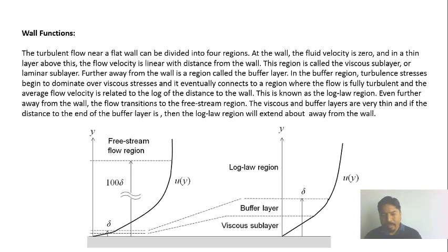It is very important while performing any computational fluid dynamics simulations to know how to capture the wall, and how we need to treat the wall. When we perform a CFD analysis, we need to understand how to give the wall functions, so that we can easily capture those boundary layers, buffer layers, sub layers, laminar layers, and viscous layers in our problem.